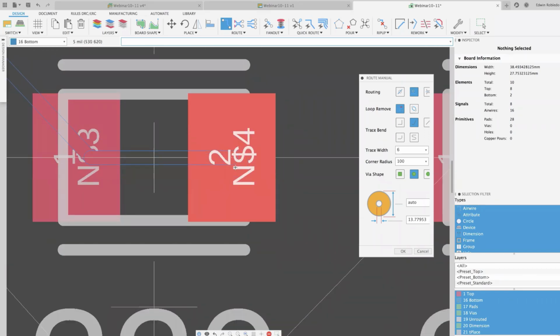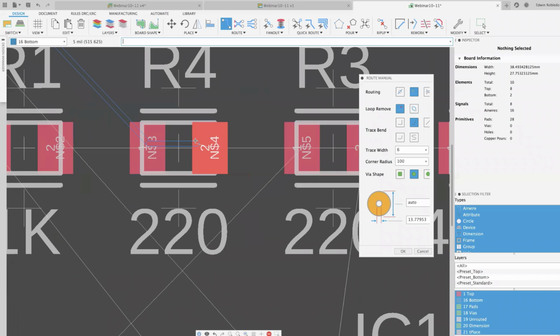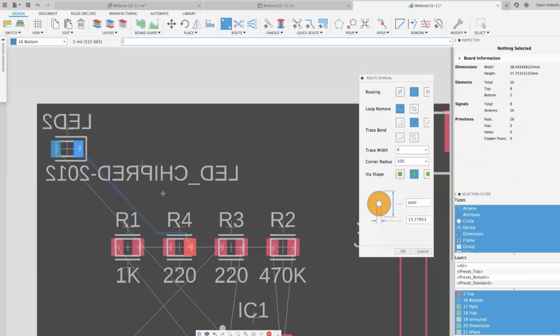As you can see, let me zoom in on this a little bit. See, it won't connect here because this pad is actually sitting on the top layer, so I can't connect to it. Therefore, I'm going to zoom out a little bit and hit the space bar once. There are different ways of doing it, but I'm just going to use the space bar because I feel it's the easiest way to do a point of transition.